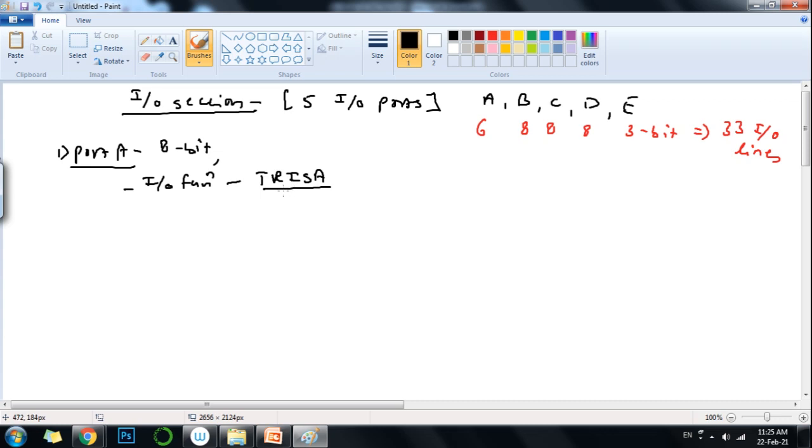There is an 8-bit TRIS register, as you know. By setting a bit in the TRIS register, you configure the corresponding bit of that port as an input bit. And by clearing the bit to 0, you set the corresponding bit of the port as an output bit. You know that, same as before.